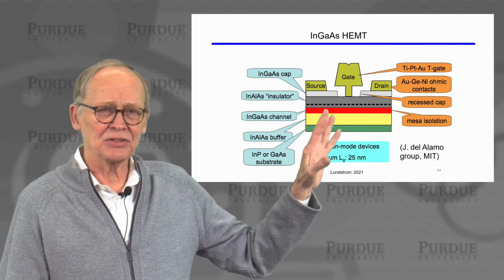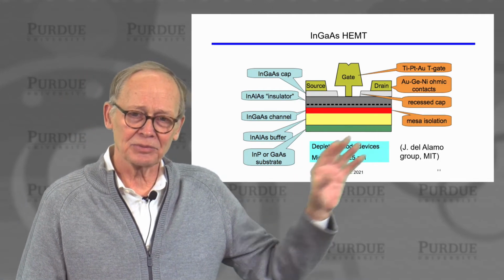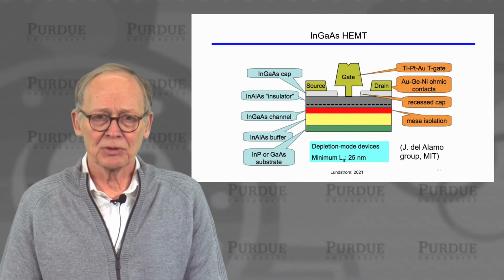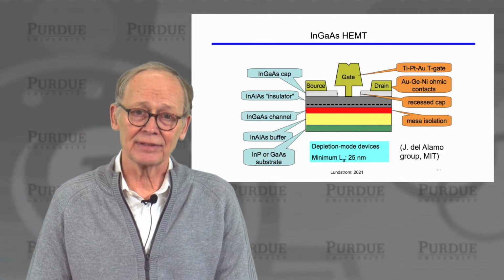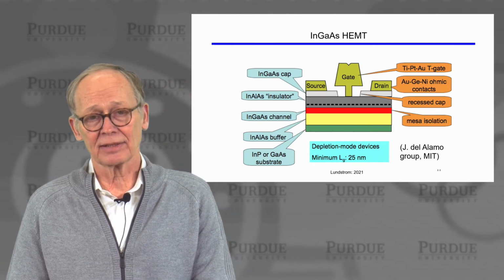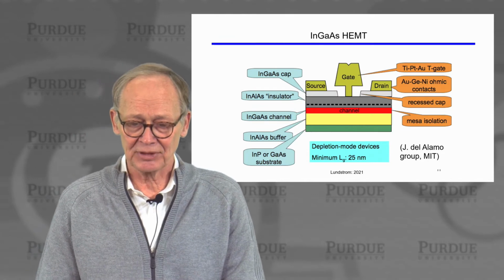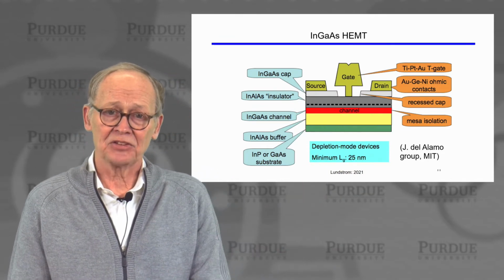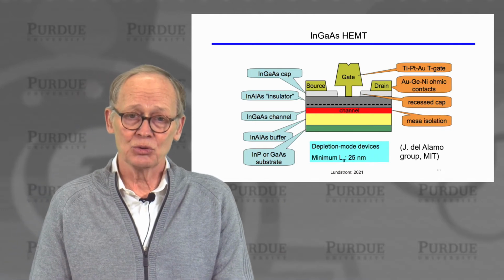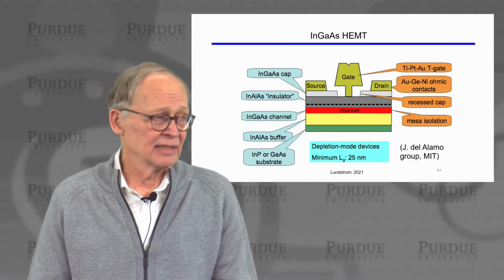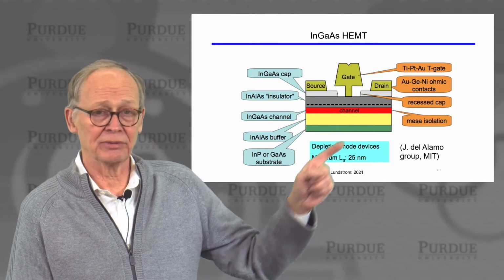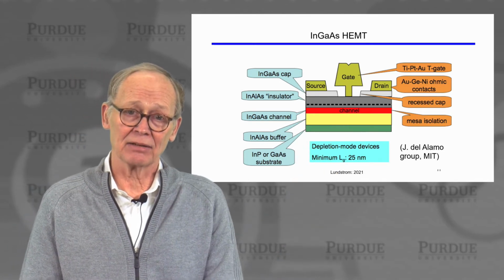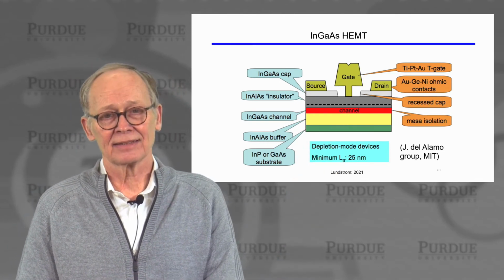They're sophisticated structures which look quite different from silicon MOSFETs. They're built with heterojunctions of different types of 3-5 semiconductors with different types of band gaps. The channel of this particular transistor is right here. It's sandwiched between two wider band gap layers, and the charge flows from the source to the drain in that small band gap channel, in that quantum well that it is confined in.